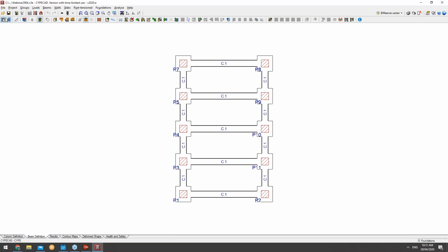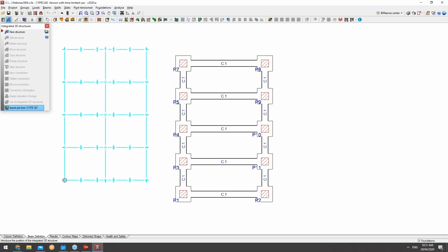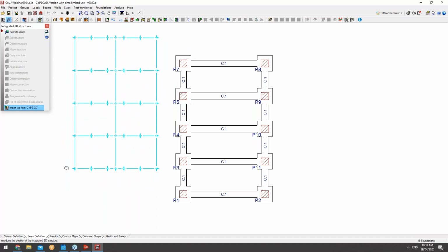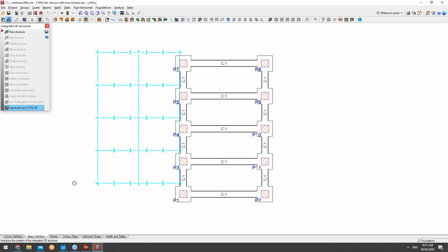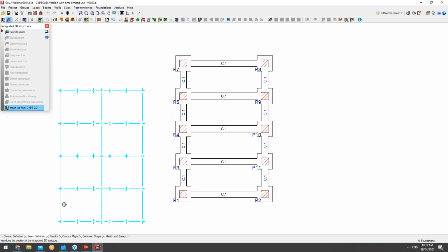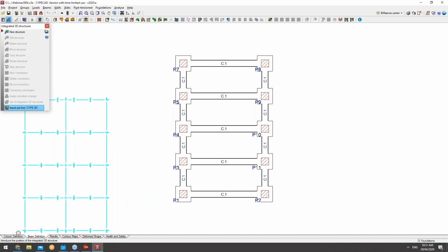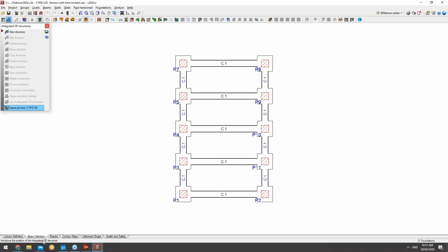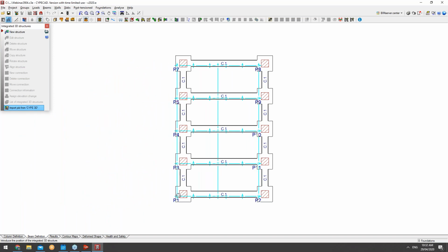Now, of course, again, coming over to integrated 3D structures here, import job from Site 3D, the webinar example, and you can see here that that particular model is shaded in blue, and I'm now asked to introduce the position of the integrated 3D structure. Now, if you don't understand what the program's asking you to do, always look at the bottom left here. It says introduce the position of the integrated structure. Now, I've selected the first bottom left-hand node.